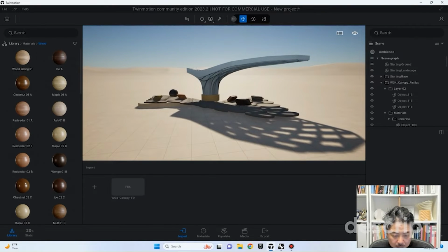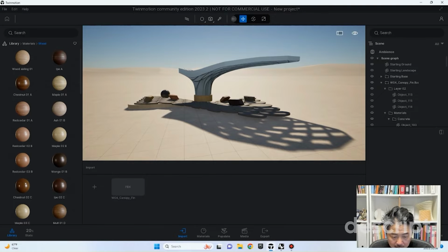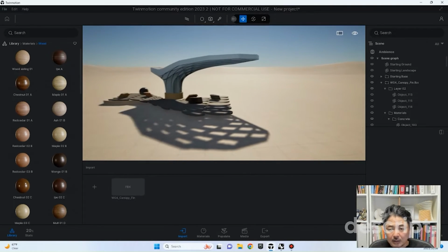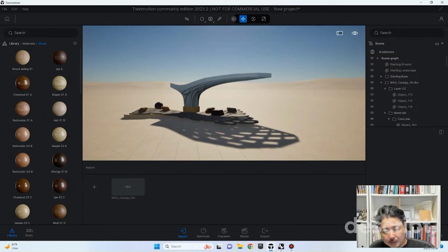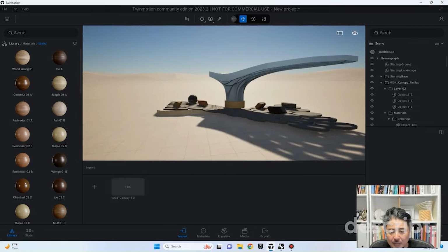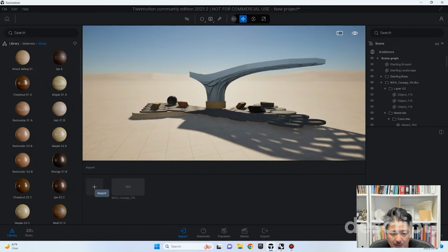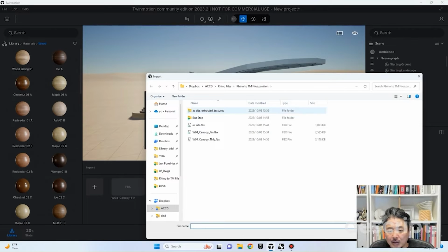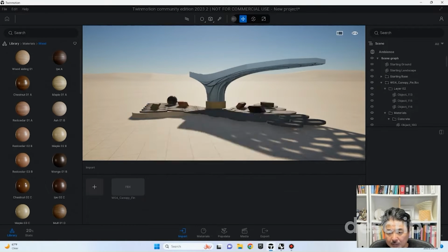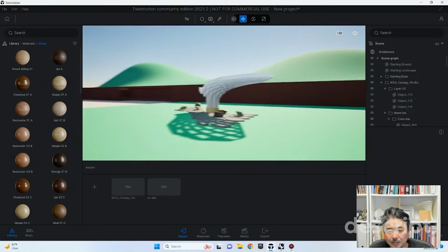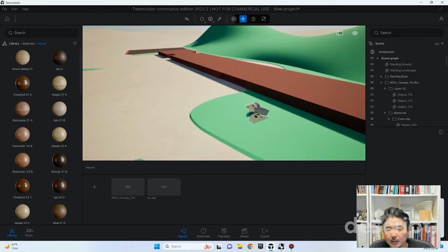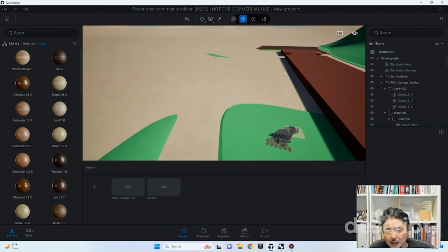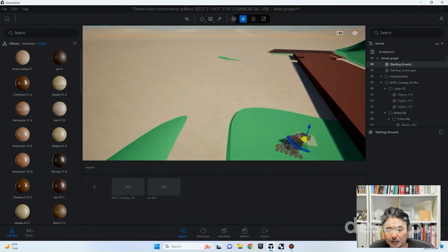Okay. So, we have applied materials and done this. For the next part, we would like to import the landscape. For today, we are just going to import an existing landscape as FBX. You can click on Import, then Open, and then AC site FBX, and do the same thing. So we have imported this site model that has the art center building and the bridge around it. In this case, what's happening is that Twinmotion's default landscape is covering a lot of it.